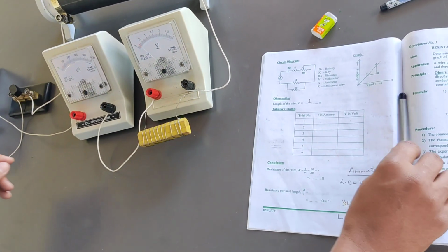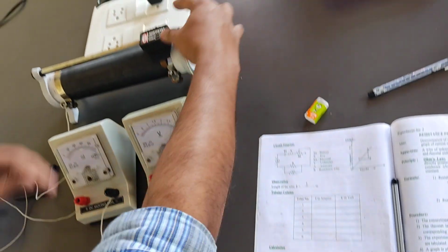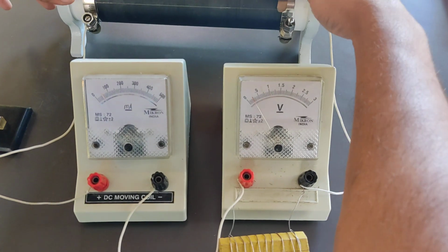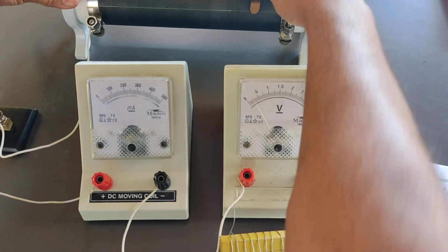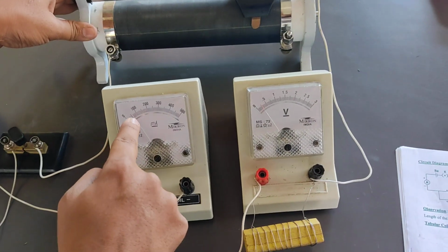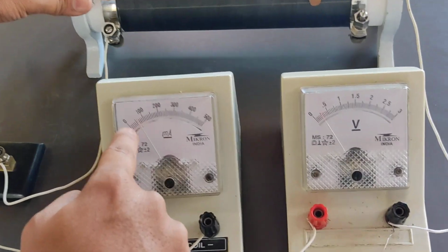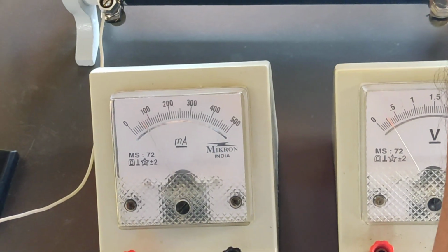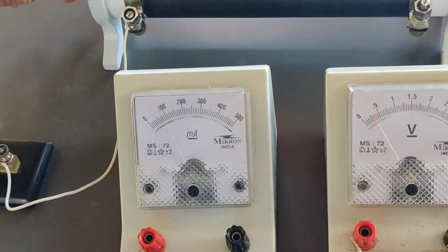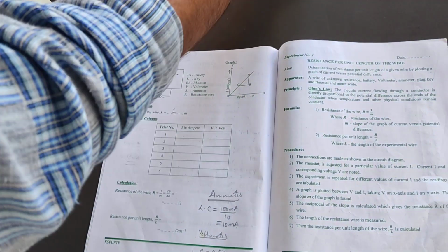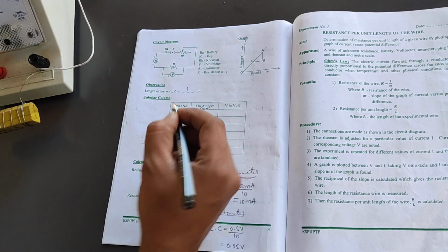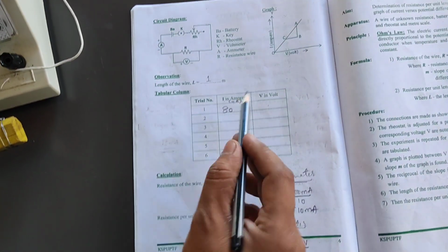Now let us start the experiment. I am going to keep one rheostat position. Here I have got some values already, but let us start with some standard values. By varying this you need to see the current. See here 0, 1, 2, 3, the bigger line is 5, in between that 6, 7. I am going to keep it at 80, means the 8th line. So now it is at the 8th line, 8 into 10 is 80 milliampere. Here you need to write 80 milliampere, and make sure the header says current in milliampere.